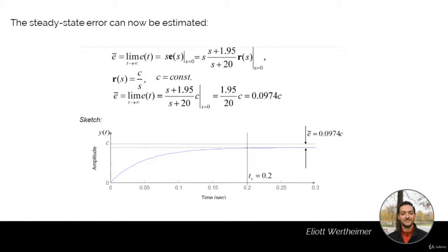It doesn't know your long-term error. It reacts to an error that is happening right now. So as this error gets closer to 0, the proportional control actually reacts less and less, simply because it scales that error by a constant value, your proportional gain. So imagine that the smaller that error becomes, the less the proportional control is going to act, until the error is so small that the control does not act anymore, and so you keep that error forever.